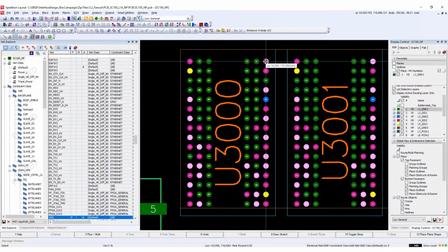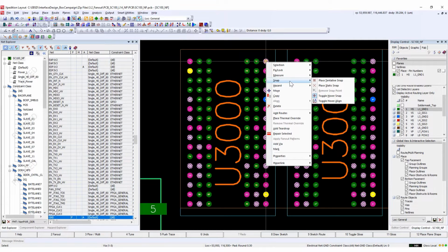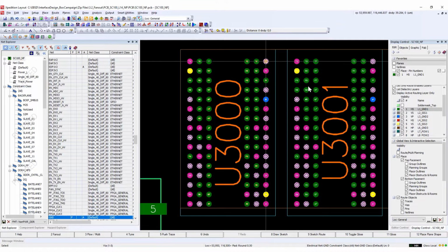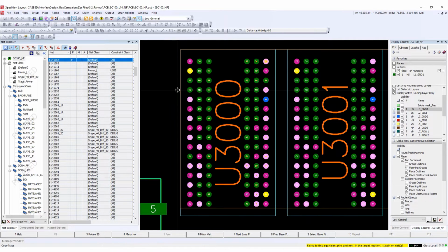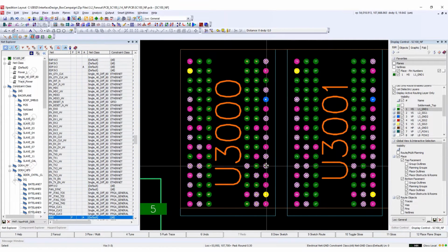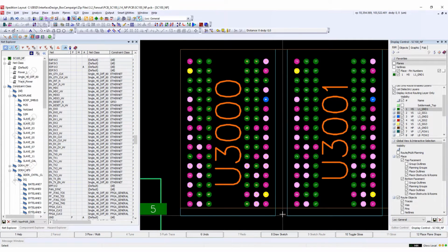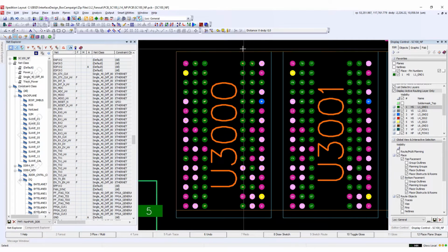Now I can use the copy circuit functionality to paste this VIA to all the other ground pins. So turning hover snap off, I'll select this VIA and use the copy command, and then with my net filter still enabled, area select the rest of the pins. And we can now see that the VIA has been placed on the remaining ground pins. So the VIA and pad fanouts for the first DDR chip have now been completed.